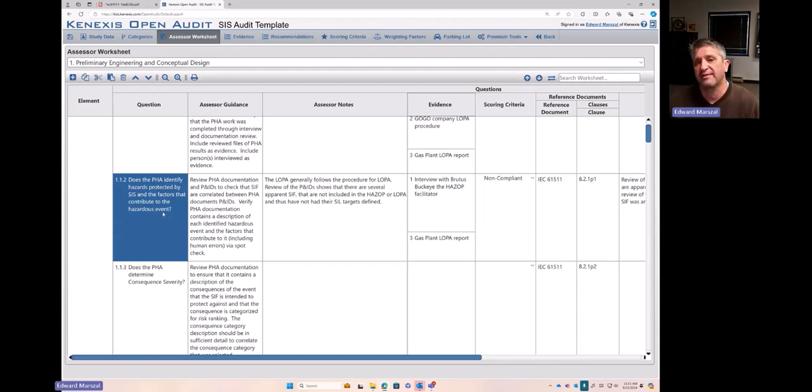But then let me kind of backstop it a little bit. If we're talking about an MOC project with one or two safety functions, a stage 3 FSA should be done with a couple people in maybe an hour. So basically that's that hour of team time, maybe an hour to review the documents and generate the report.